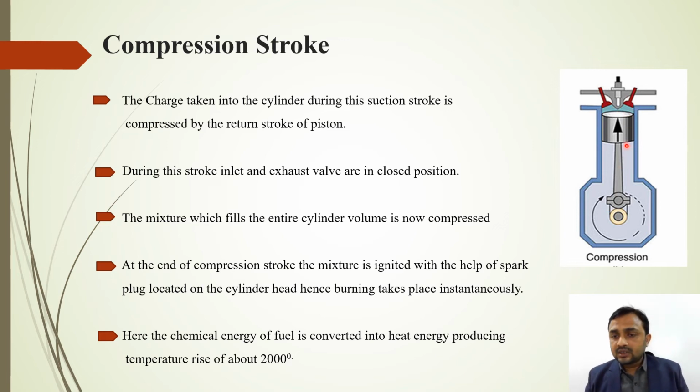Okay, because if one of these valves is open, then the air fuel mixture can go out with the help of this valve. So that's why your inlet valve and exhaust valve, these two valves, are closed in case of your compression stroke. Third point is the mixture which fills the entire cylinder volume is now compressed. The air fuel mixture which is inside the cylinder from your suction stroke, the entire air fuel mixture gets compressed in your compression stroke.